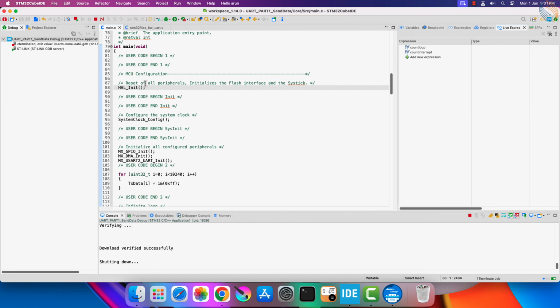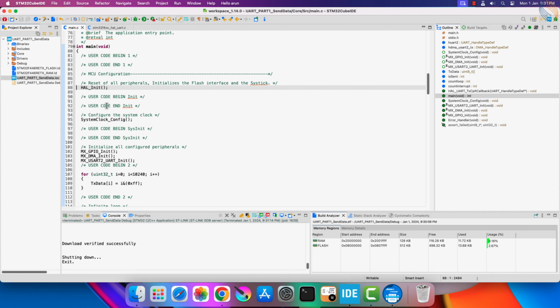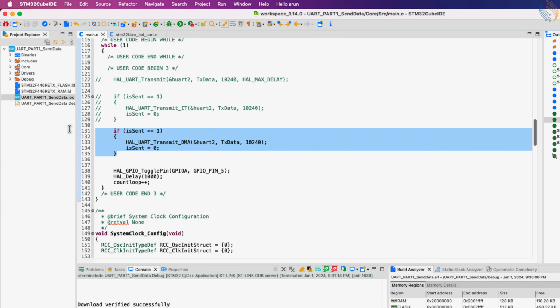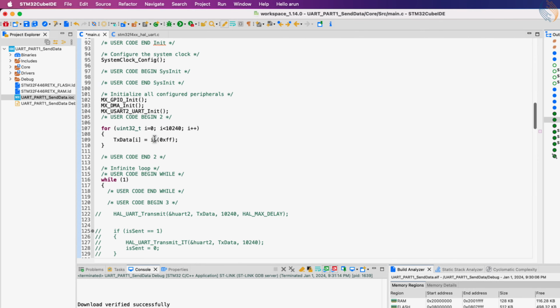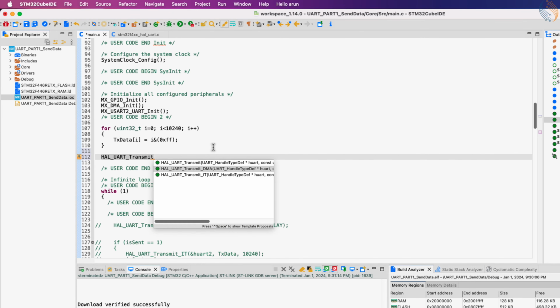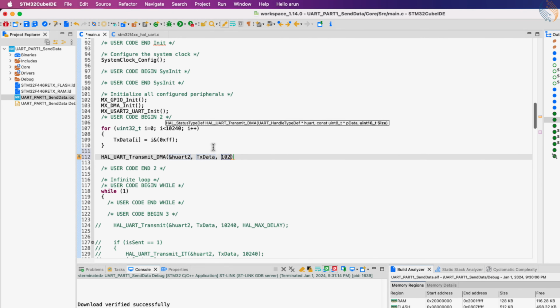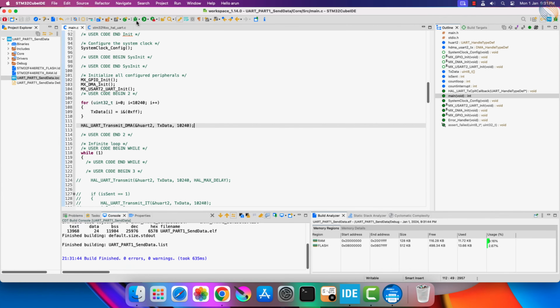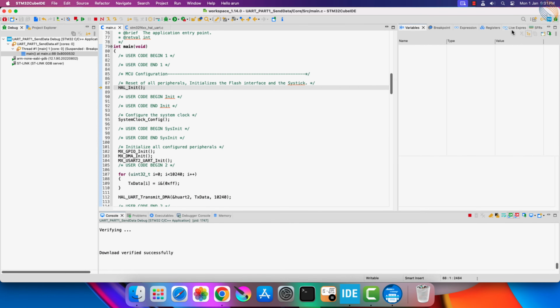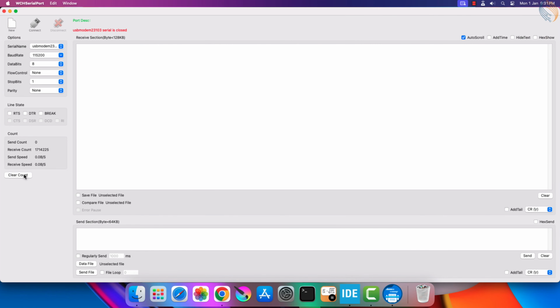Now while configuring the DMA we came across the DMA modes, the normal mode and the circular mode. Right now the DMA is configured in the normal mode, and in this mode the DMA does not reload the address after the transfer is complete. Basically it transfers the data once, and after the data has been transferred, the DMA stops. Let me show this by calling the transfer function outside the while loop.